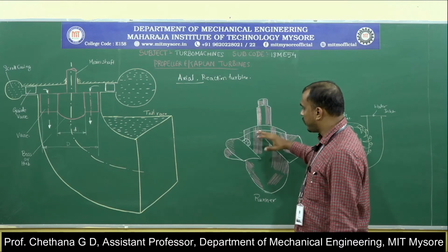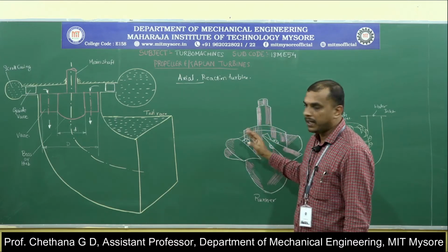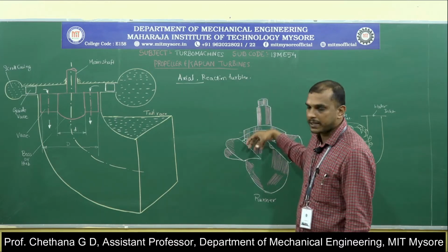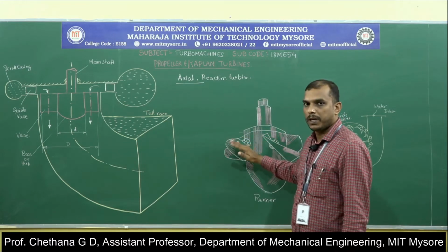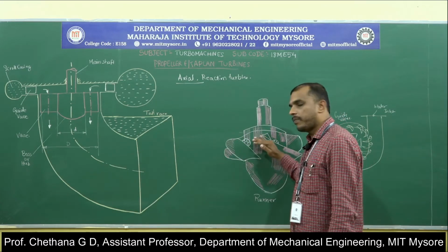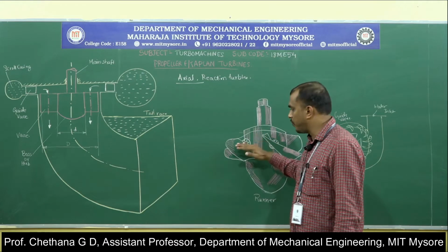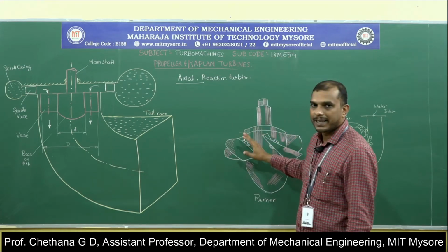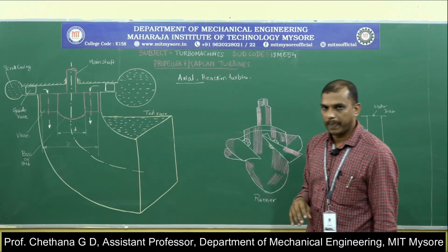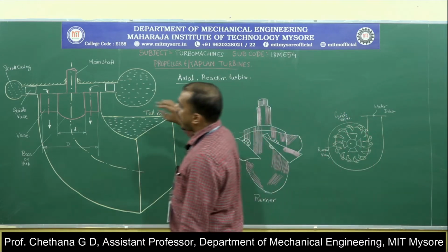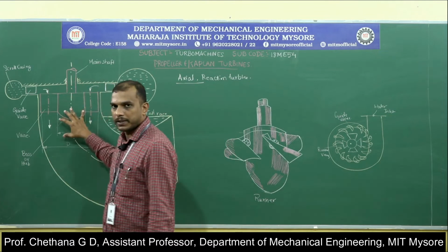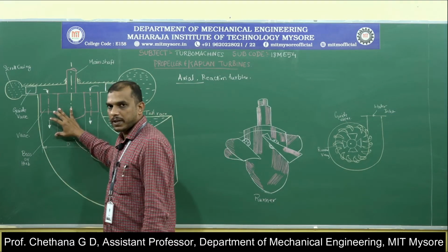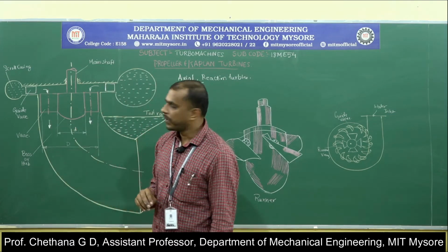Now you know when you change the angle of the blade? Whenever you have higher discharge, these will be getting themselves vertical, okay. Whenever you have low discharge, the tangential component will be higher. So after extracting the energy, it once again leaves the turbine axially.